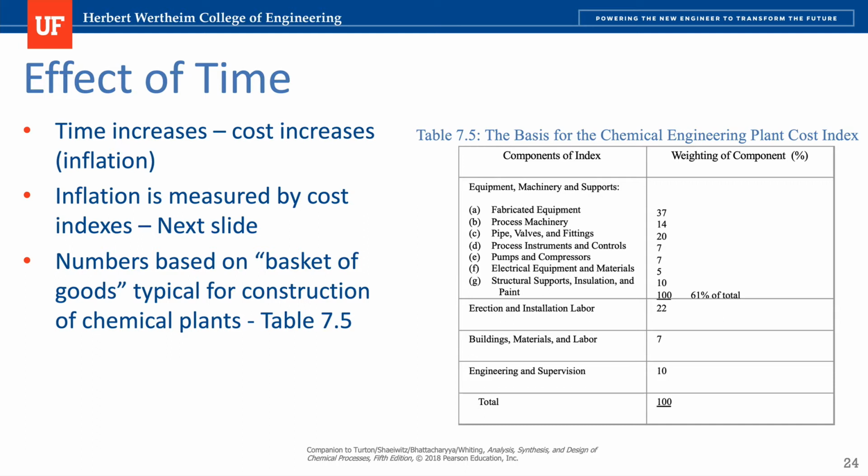And then you also have engineering and supervision, which is the payment that is a shared cost between multiple projects, but you typically include it there in your cost. The different magazines collect a lot of data across the many industries, so that's why you have multiple cost indexes depending on the industry, and that data is updated every year. Okay, so right now we have for sure the 2020 data, so 2021 is not yet published. It happens every quarter, and everything is an estimate in the current year until we get the final value at the end of the year.